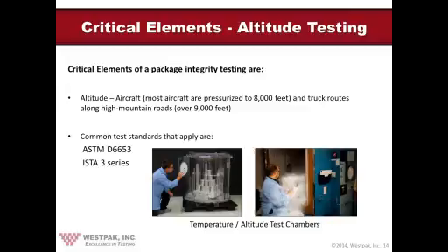So there are obviously some war stories about it, but anytime you have a closed vessel, either in the product or the package, for example, a closed cell foam material, it is going to expand in response to reduced atmospheric pressure that occurs at higher altitude. So don't ignore these subtle little things.